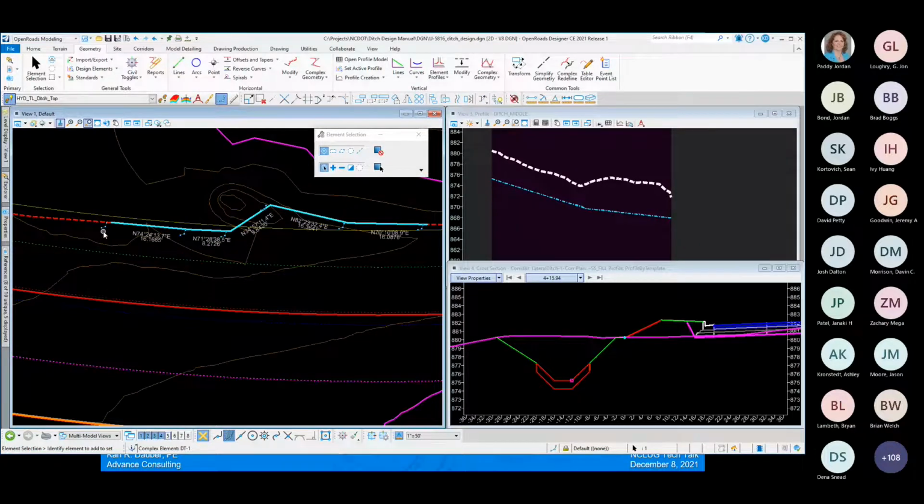I want to see these snap glyphs, these indicators that I have snapped to, and now there's a rule making that dependent on the slope stake line. And notice that the text manipulators are all gray, showing that I can't edit them because this alignment is now ruled to the slope stake line.